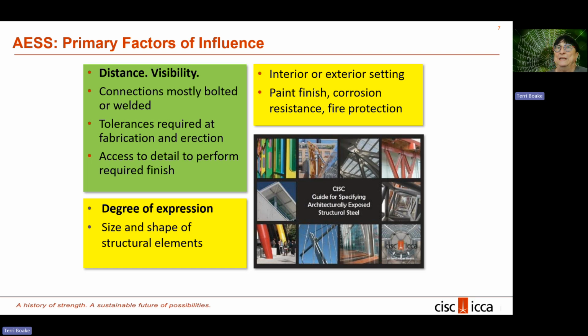It will really depend on the degree of expression in your project, as well as the size and shape of your structural elements. Things that would be of concern in a major project would be whether it's an interior or exterior setting, because that's going to start to impact your fire resistance requirements as well as your corrosion issues.